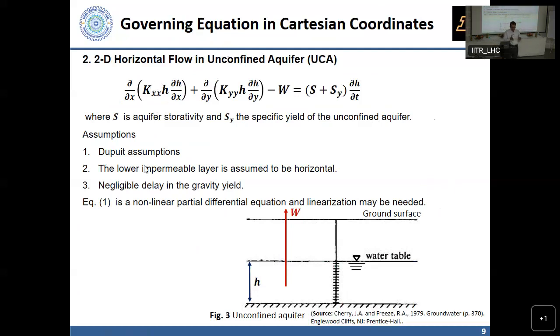So out of the total pore space, a fraction of it, S sub Y part, is from where you can remove water. The rest of it is essentially not going to be released at all, unless you do something spectacular. It's not going to happen, let's say, in field conditions. You have to bring the soil to the lab and oven dry it to get rid of that portion of the water. So total porosity, therefore, is composed of the S sub Y part plus a part that the soil